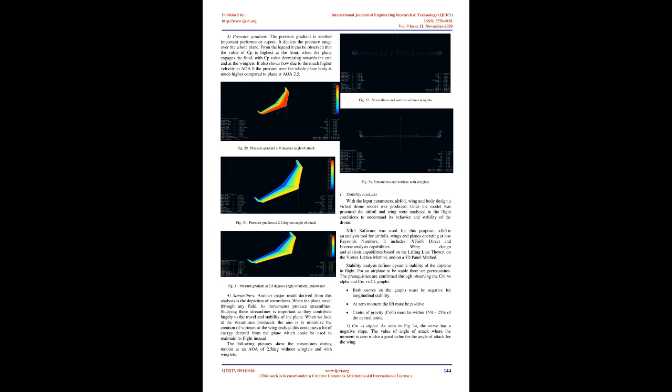C. Wing design. After thorough analysis of the foil, determining its operating range and the right AOA for the required application, the wing design is begun. Wing design includes designing of the flying wing connected to the main body. The software XFLR5 is used for this purpose. The dimensions of the wing were determined initially through wing cube loading. As seen in Fig. 15, the data of chord length, span, sweep angle, dihedral angle, and twist are determined. Through adding multiple sections, winglets are also included.